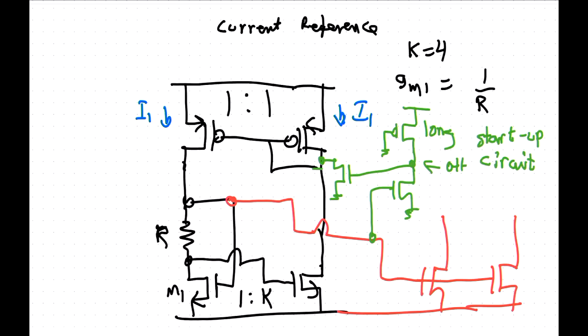So if this is your input, then you've got to lower the drain current. That's why it's a secondary part. The output stage doesn't matter. The input matters for the noise. If your input stage looks like this, with a current input that goes into the source, you get this current here. That's the noise, and you want to keep it low, so you want to reduce the current here.